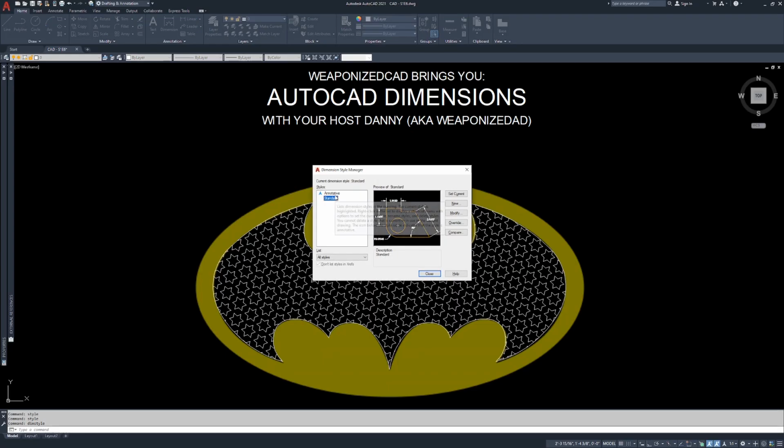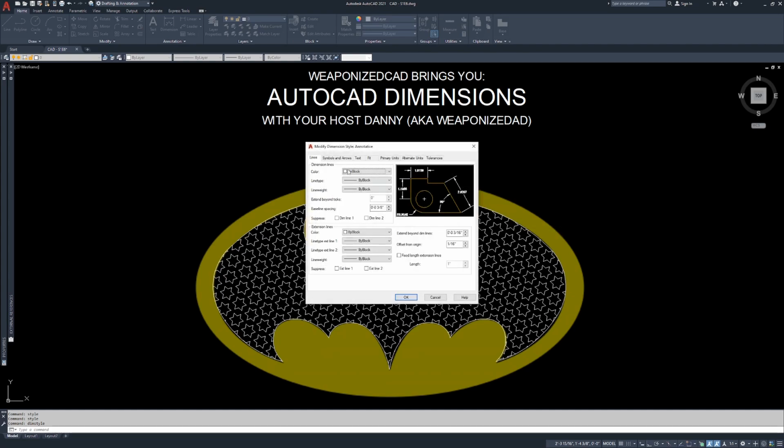In dim style, we want to look at our annotative dim style. We want that set to current. By double-clicking it or clicking the Set Current button, it's going to say Current Dimension Style Annotative. That's what we want. We want to click Modify. Most of this is going to be okay. After we get some dimensions in, we might want to tweak it. So we'll throw a couple dimensions in. If they look absolutely ridiculous, we're going to tweak them in here, and this is going to update any dimensions under the annotative style.